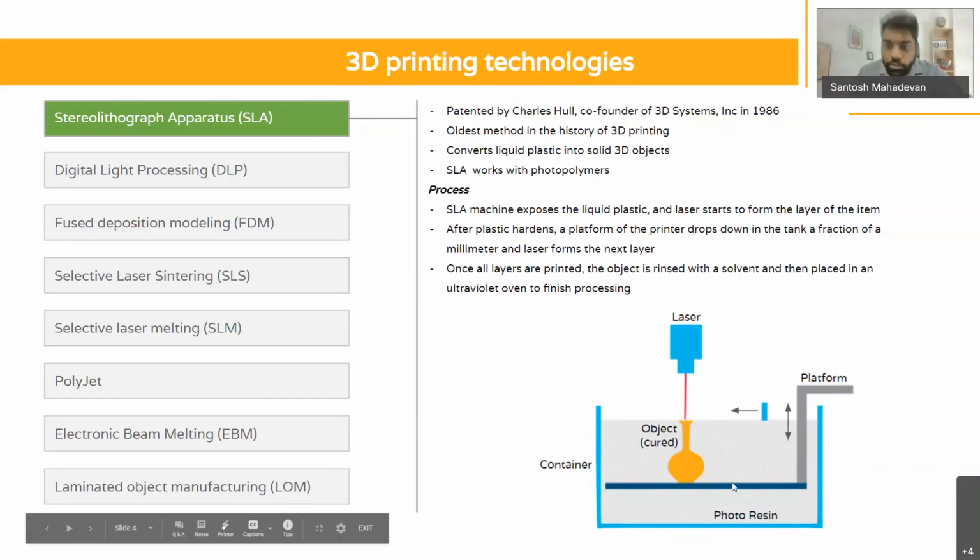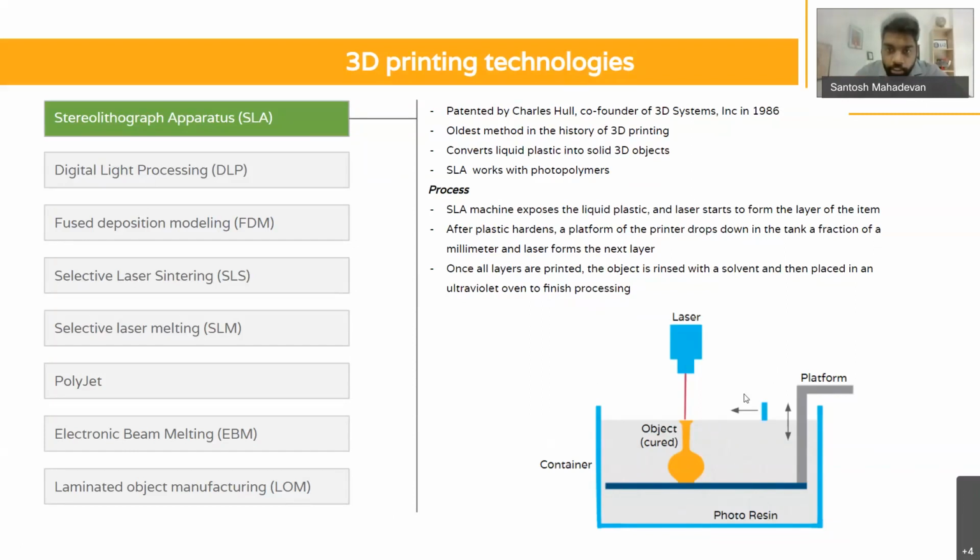Now, as I told you, in 3D printing you have to join layer upon layer upon layer. It does not mean that you are going to cut an object into an indefinite number of layers. You are always going to cut an object into a definite number of layers. You are going to know the number of layers that the object is going to be made of beforehand, and you do this by deciding the height of each layer.